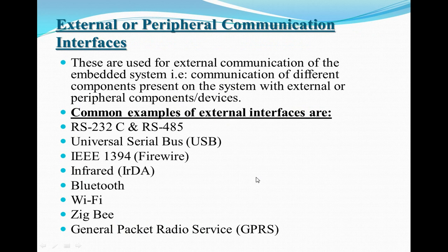This SCL is going to generate the synchronization clock pulses, and this SDA is going to transmit the data serially across the devices. So if you are going to connect the LED and the microphone, or the audio sensor and the microphone, the communication has to be sent bit by bit, the clock pulses have to be transmitted and it has to be received accordingly.